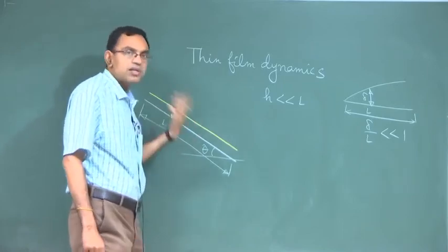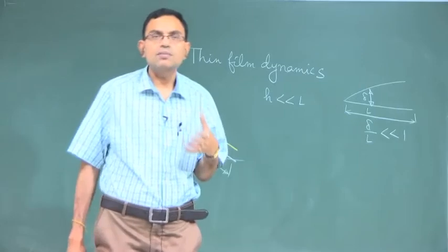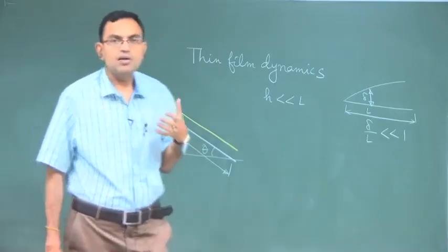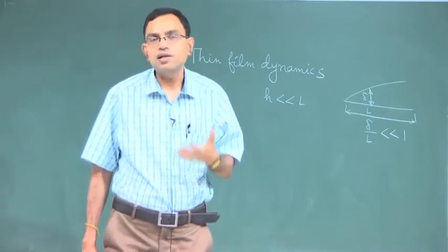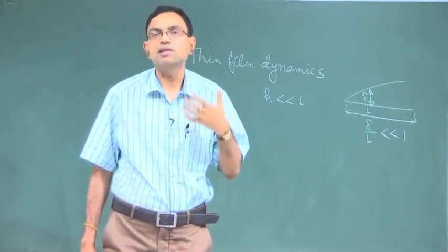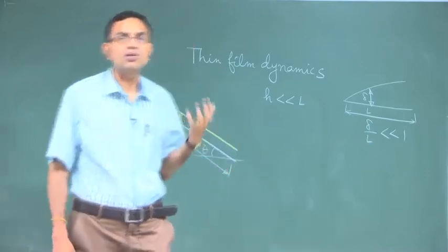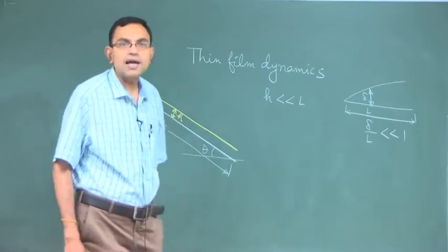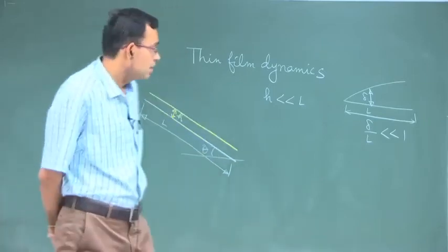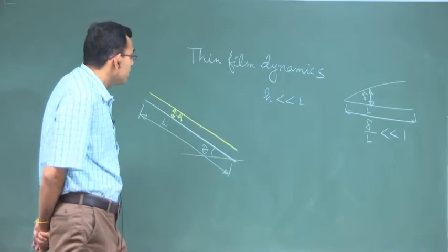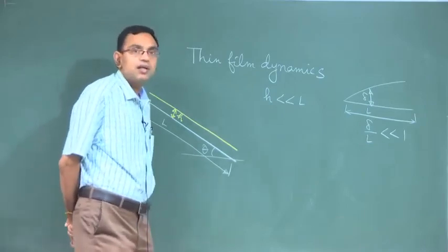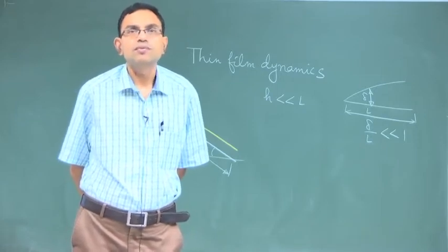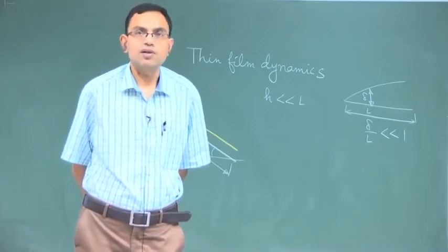There are other forces which are equally or even more important, not just viscous force and inertia force: surface tension force and gravity force are also very important for thin film dynamics. So, Reynolds number alone cannot decide anything, but in most situations in thin film dynamics we are concerned about flow at low Reynolds number.